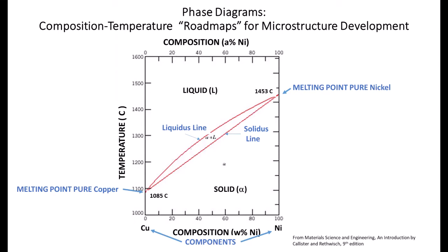In this type of phase diagram, copper and nickel, both metals are FCC cubic metals having atoms of nearly identical size, allowing the formation of a continuous solid solution from pure copper through pure nickel, meaning there are no other crystalline structures or phases that form between the two pure elements.